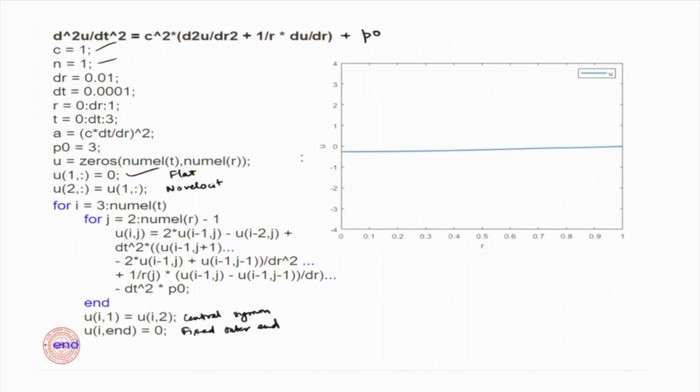This is your displacement u, and the displacement exceeded and went up. This is the maximum displacement that you can get. Let me run the animation one more time. Again, you see that u is the displacement, right? Not xy. It's the r coordinate, and then the displacement reduced, and then the displacement again went back to 0. It exceeded 0 and it came back, and it will keep on oscillating. The oscillations will gradually dampen out if there is a damping factor and come to a steady state. If there is no damping, then it will keep on oscillating.